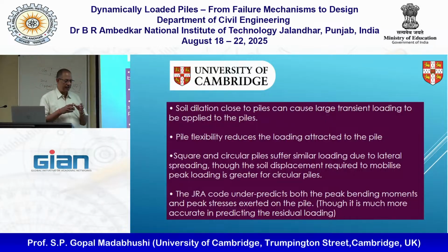And as liquefied soil wants to go past the pile, it gets sheared, and if it gets sheared, it tries to create suction, and that means it gets stronger, therefore it can apply bigger load. This is the underlying mechanism that is causing us all the trouble with this problem. Okay?